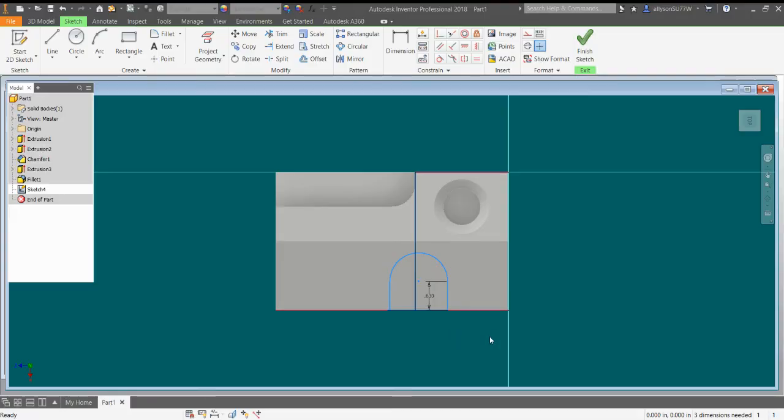Right click and OK. So now we are out of our line tool. We have our dimension here for our height, which is 0.630. Before I put the dimension on my arc, I am going to move this tombstone over so that the center point of the arc is on this line. I can now come and dimension this arc, which has a dimension of 0.5. Notice it adjusted my tombstone.